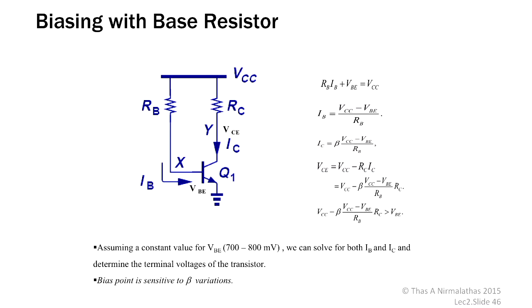So when you have a band gap reference, that produces a golden current. We call it a golden current. You will study later in the constant current source, when we study current mirror. The band gap reference will generate a golden current that will be constant irrespective of the temperature. So even though you put in a battery, because you have this band gap reference circuit, your mobile phone performance is not affected when you take it to different countries having different temperatures. But most of the time you don't have a band gap reference readily available, which means we integrate the band gap reference in the chip. If you don't have a band gap reference, when you increase the temperature, this VCC will increase.